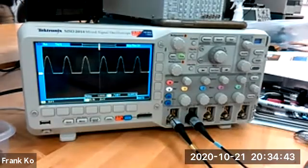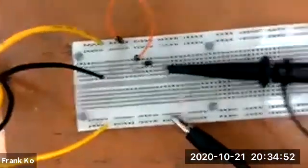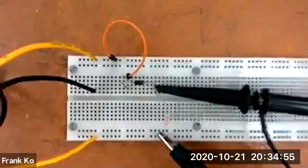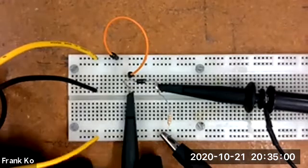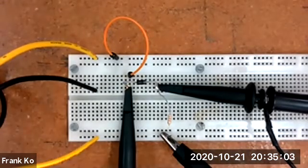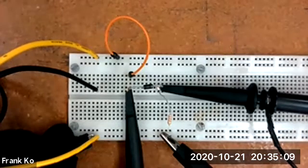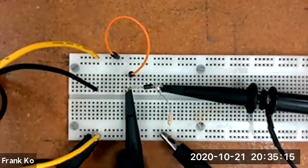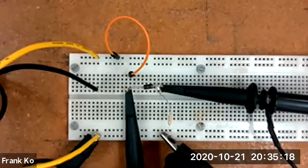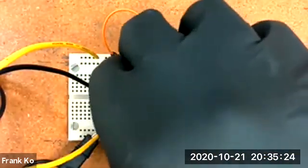And when you plug it into channel 2, this is how you're going to connect it to your circuit. So let me go back to my circuit. Watch carefully. The oscope probe will go to the front end of your diode, right there, and the alligator will connect to your bottom bus rail to your secondary. So your two alligators are hooked up to the same rail at the bottom of your circuit, and your second oscope probe just lifted